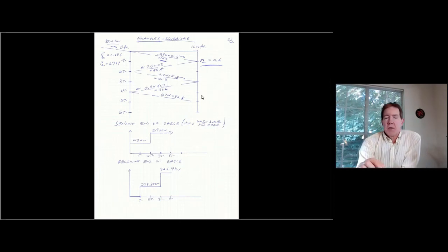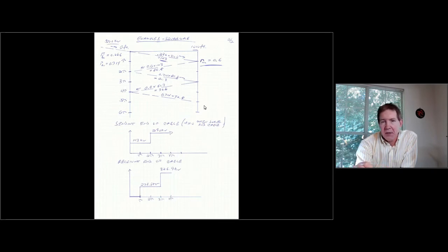So I'm doing this for a relatively short period of time. If I'm calculating what the impact is going to be at either end, I basically have to add all the voltages up as they change. So if I wanted to know what's going on here, it'd be the 143 plus the 85.8 plus the 61.3 plus the 36.8 plus the 0.714. I've got to do the bookkeeping. I've got to keep track of all those different values, right?